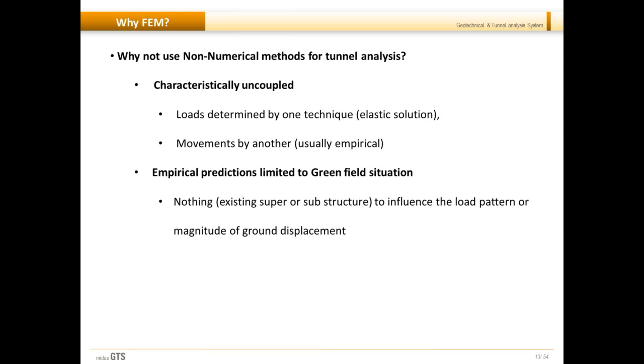There is no superstructure or substructure in the vicinity to affect it, and they are not realistic because they don't consider the pore water pressure changes, the plasticity behavior of the soil, the lining deformation, the existing structures and their effects.